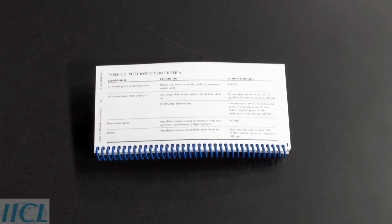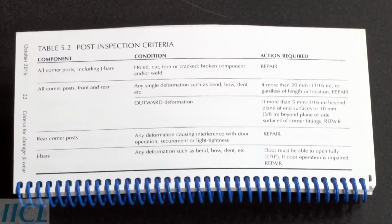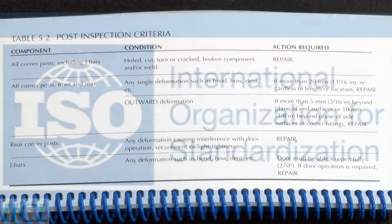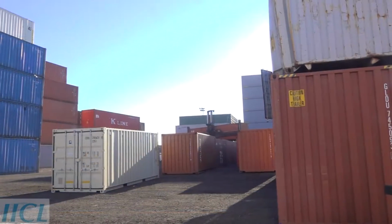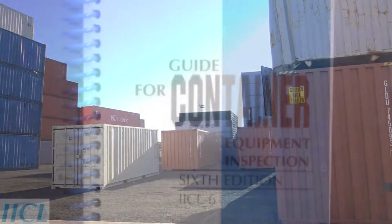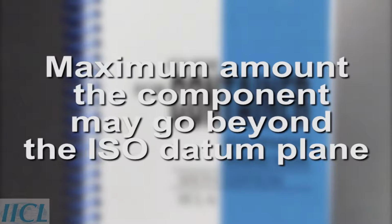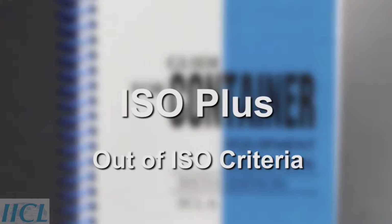Alternatively, the criterion can specify the distance from some datum surface beyond which the component is not allowed to go, called an envelope criterion. The datum surfaces specified are usually the standard surfaces that the International Organization for Standardization, or ISO, uses to specify the envelope that a container must fit within. As these types of criteria are usually specified as a maximum amount the component may go beyond an ISO datum plane, they are commonly referred to as ISO plus or out of ISO criteria.